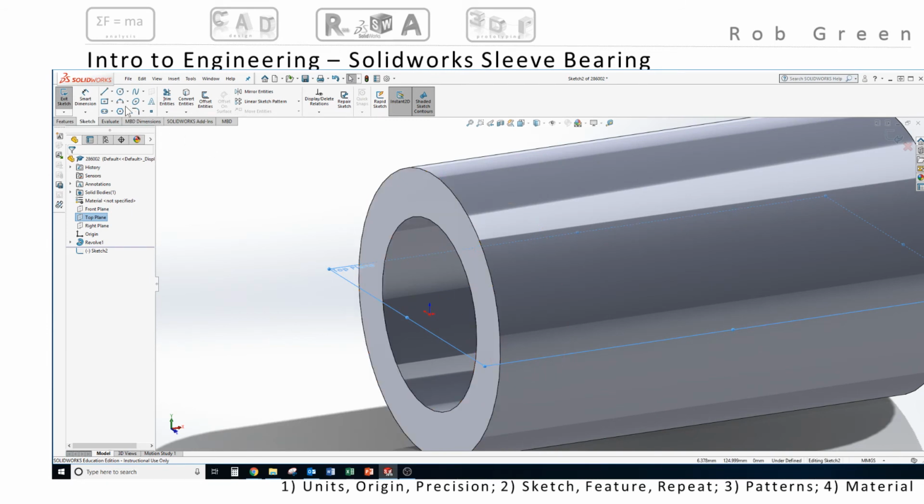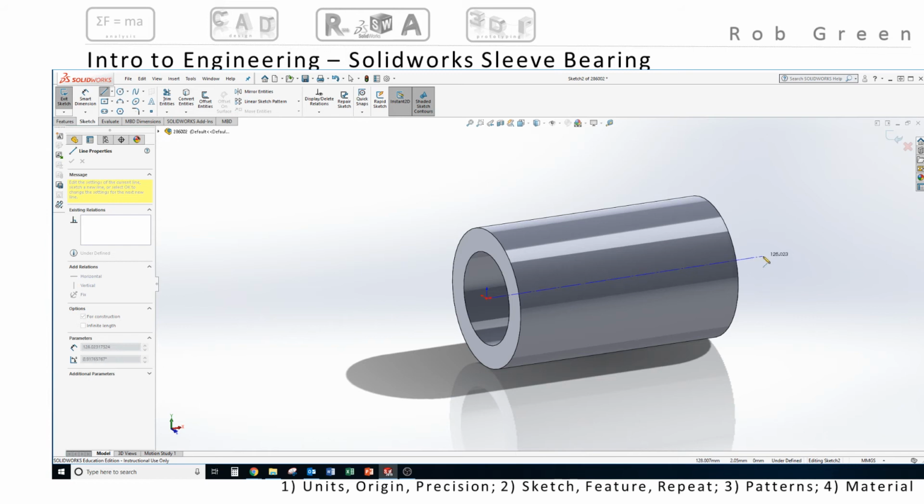I'm here also going to start by drawing a center line. Make sure that I click onto the origin and move off to the right. And I'm going to kind of look for that yellow horizontal box. Once I see it, I'll click my line into place. I won't move my cursor at all, and I will type in my length to be 100 and press enter.